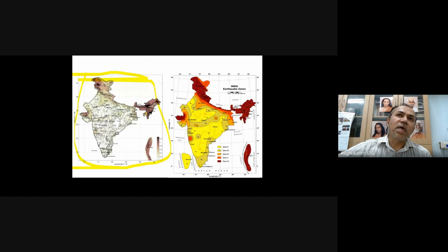So from the contours, how to develop this zone map is a big issue. Here we have done several procedures, like the statistical natural breaks algorithm. Then we have smoothened the contours using statistical techniques such as spline fitting and others. So we have come up with this smooth zone map of India. Right now you can see the whole India has been divided into almost 5 zones basically.